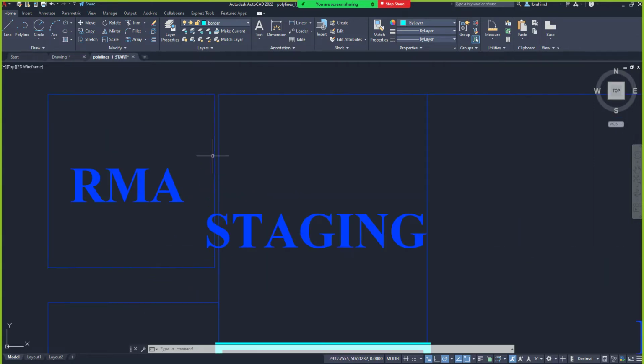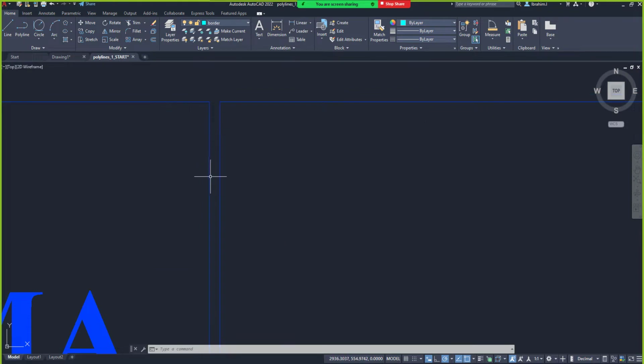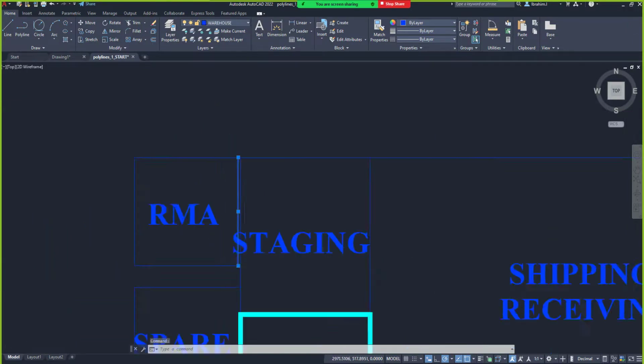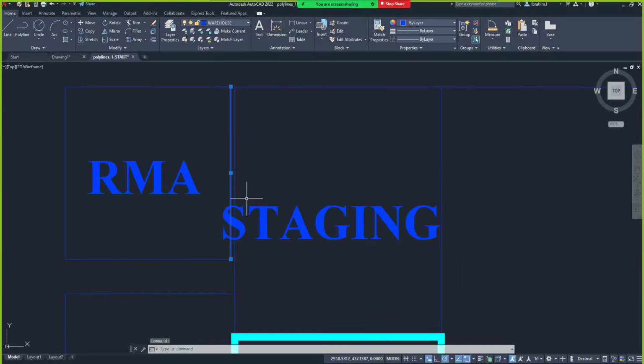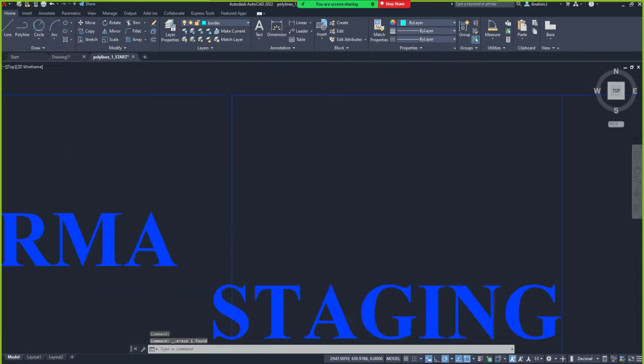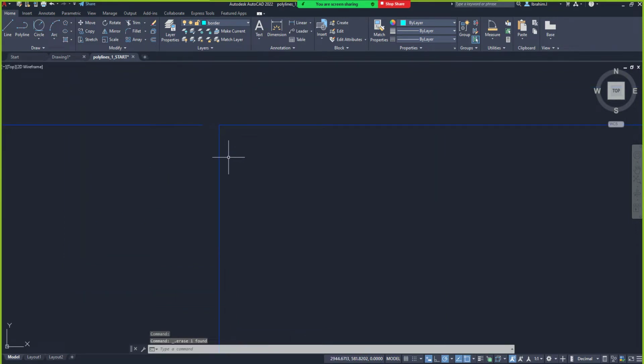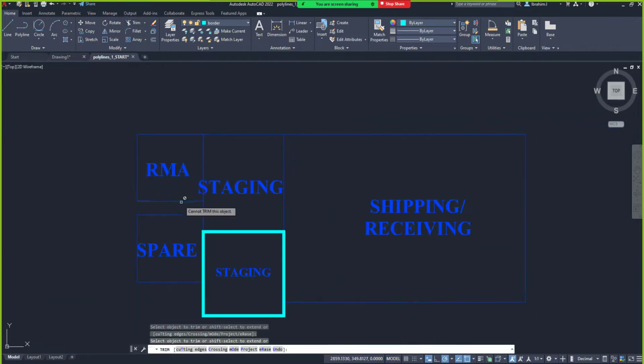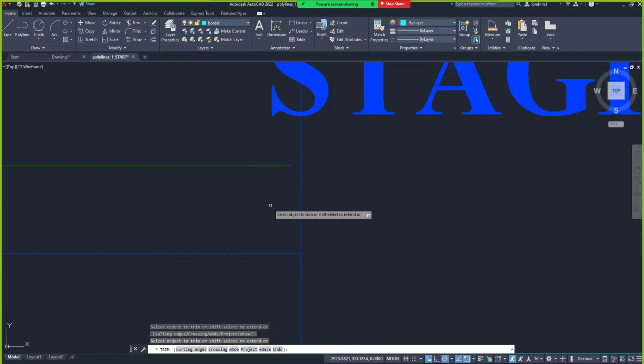The first one that I believe everyone should know: can you see there's a gap in this window first? Yes. I don't want this gap. This is a mistake. So I can delete one of the line segments that is here. Can you see this line segment here? I'll delete this, and then you can see that line is not touching the other line here. Right? I will use a command that you don't know, but I'll just extend. I'll do what? Extend. Are you with me?